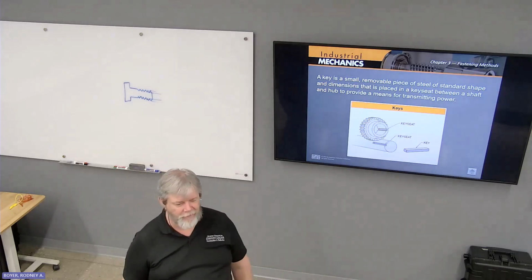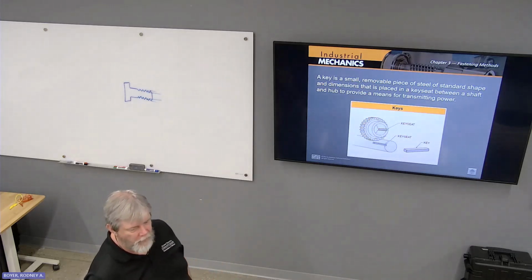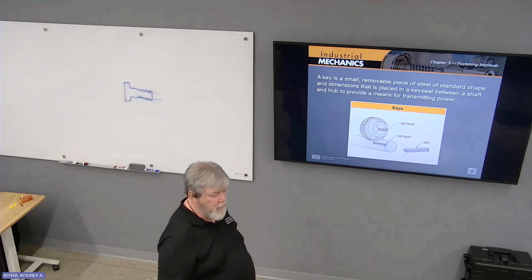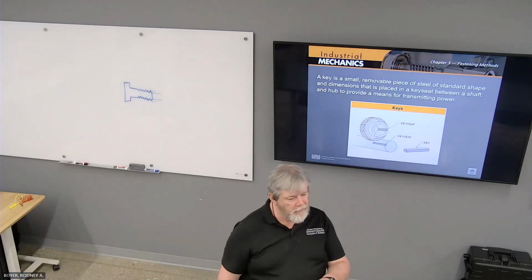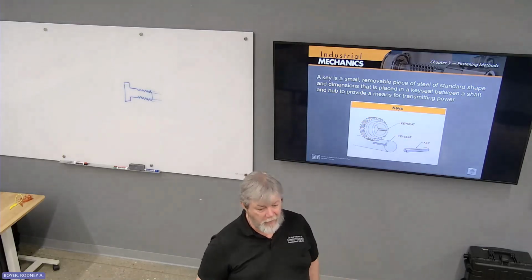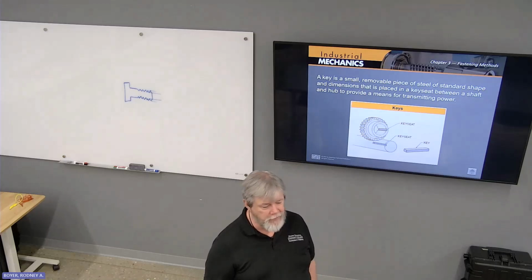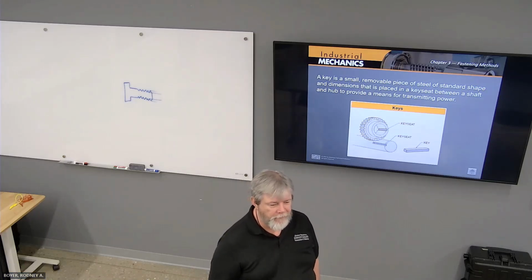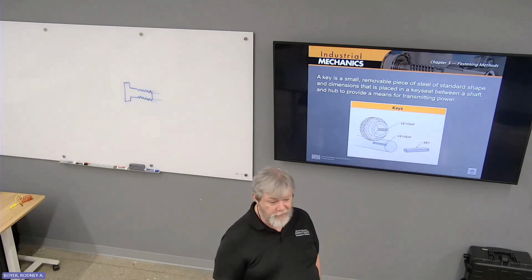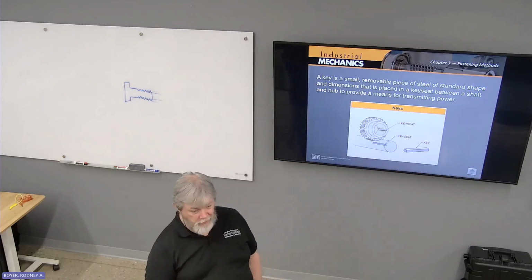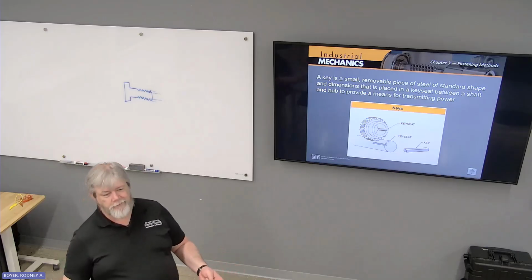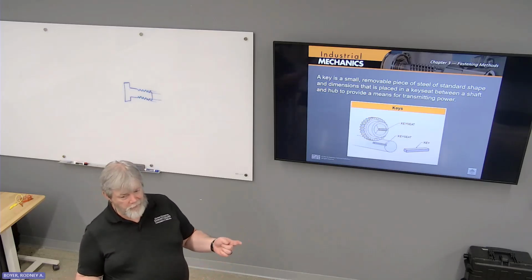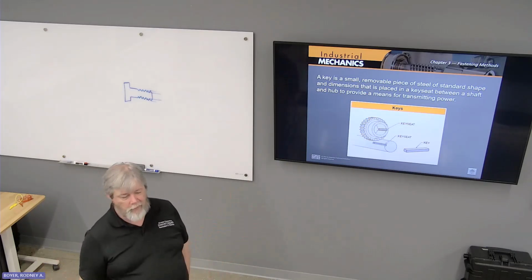What's the flywheel? So what is it? Oh, the flywheel is typically just cast aluminum. And it has some kind of ferrous metal embedded in it, and then a counterweight on the other side, so it's balanced. Yeah, it just changes the ignition timing, and if you don't have the spark when you need the spark, you can still have a spark, but it was at the wrong time, so nothing happens.